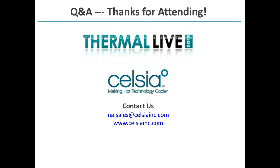From a cost, so you have a vapor chamber solution, and you want to change that to a heat pipe solution. The cost for the heat pipes themselves is generally lower than for the vapor chamber. But you have to look at how many heat pipes you're going to need, and then what's the cost of installing those? Do I need to machine some fancy grooves into the base, or are they just straight grooves? Or in other words, how much is my machining cost going to be?